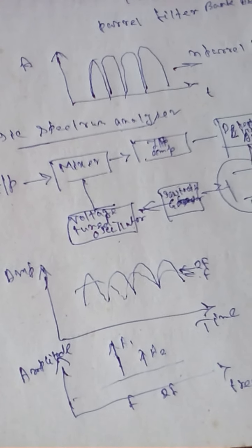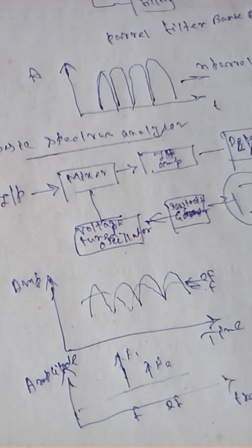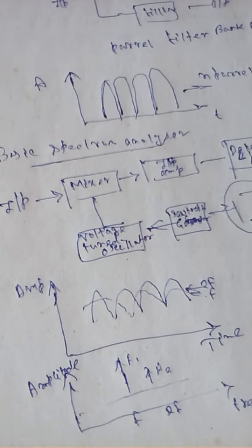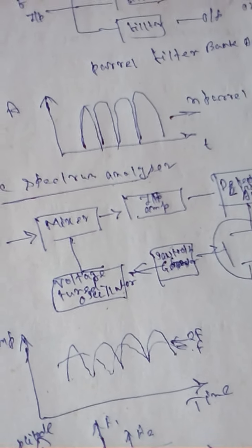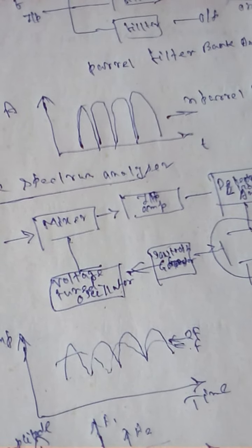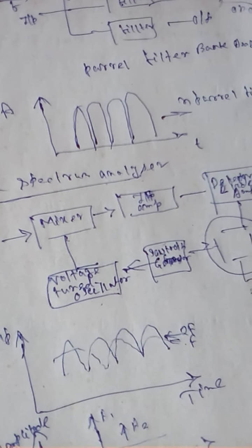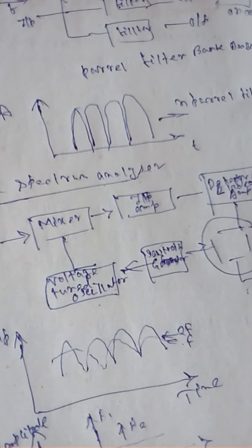Now take the radio frequency wave analyzer, meaning the RF spectrum analyzer. A practical example is the RF spectrum analyzer, a microwave instrument. Microwave instruments can have a horizontal frequency axis of 2 to 3 gigahertz for broad and narrow frequency ranges, highly magnified.